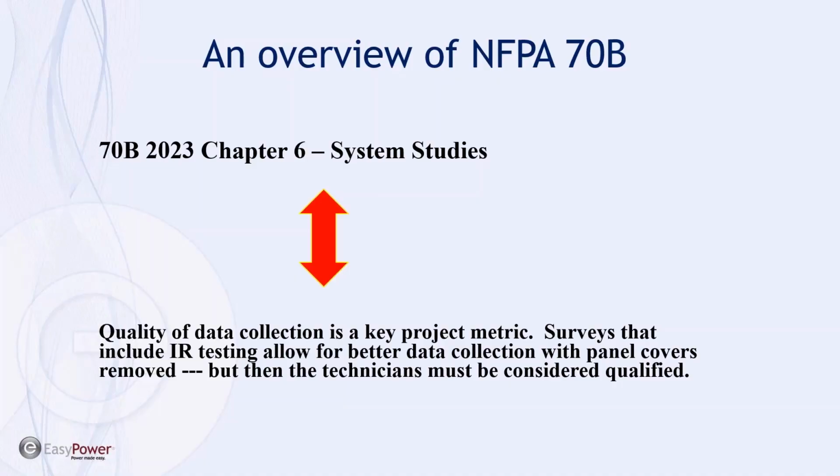As you begin the process of inventorying your electrical system, how deep does your inventory go, and do you develop the additional specifications needed that are used by the engineering software to support those other studies? For example, will you be recording the AIC ratings on breakers that are literally listed right on the devices themselves? Are you recording wire sizes and distances as you inspect those individual electrical components? Because those are some of the elements needed to ultimately develop the incident energy model.